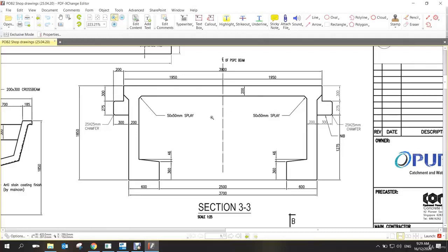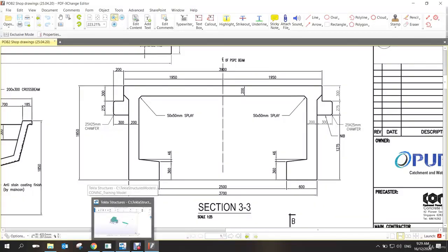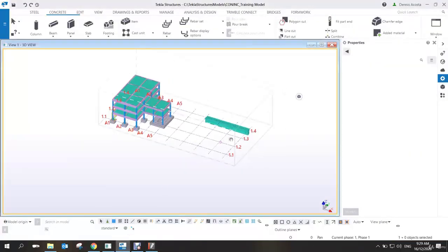All right. Okay. So we're going to create this section using the sketch parametric cross section. Since you mentioned that this one is parametric, meaning you can change the width and then you can change the height. If it is fixed, then I would suggest that we use the CAD to 3D. But since this one is parametric or has some changes, we need to do that one on the parametric cross section.